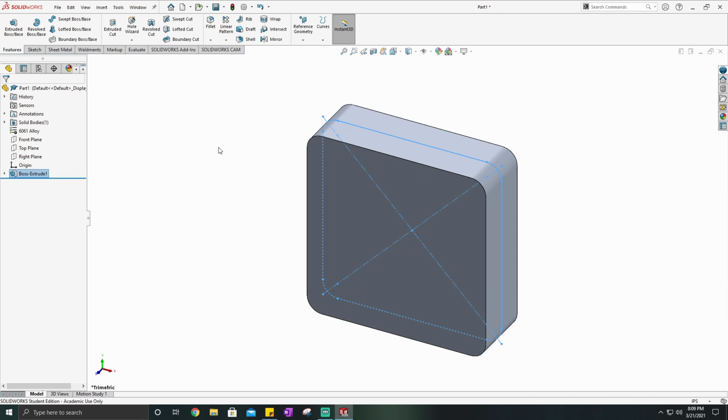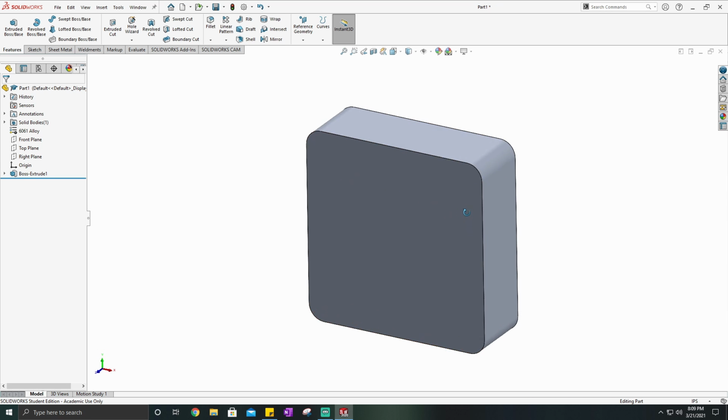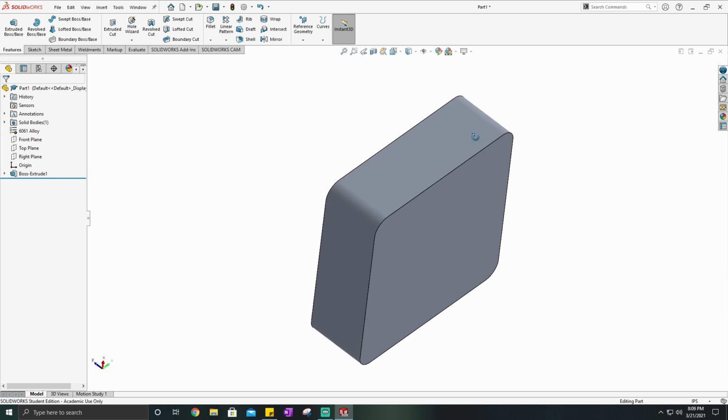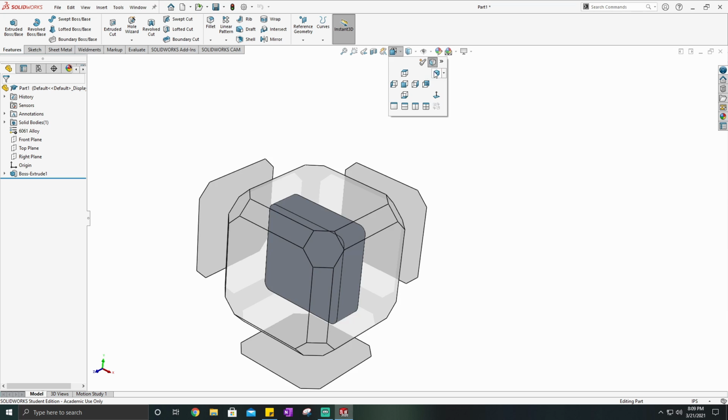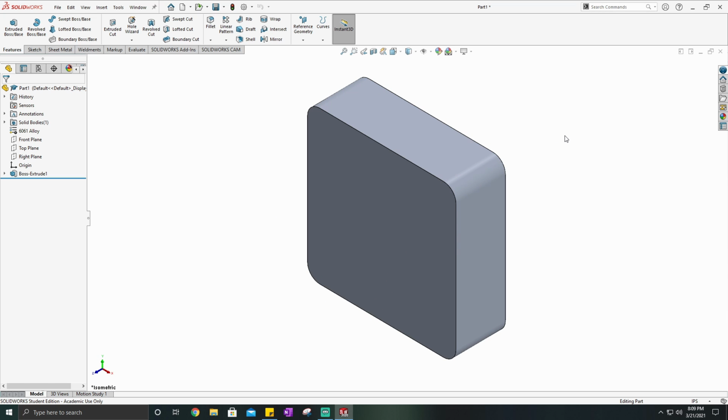We'll go ahead and click check, and SolidWorks turns this into a physical model. Again, if I hold the middle mouse button, I can rotate this, and you can see that there's a physical model. In the previous video, I talked about one of the settings that I had called tangent edges turned off. What that basically does is, as you'll notice, the part looks smooth, but yet when I hover my mouse over it, there's a face, a curved radius, and then another face.